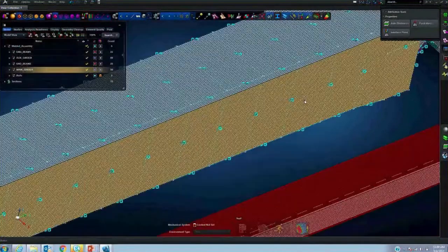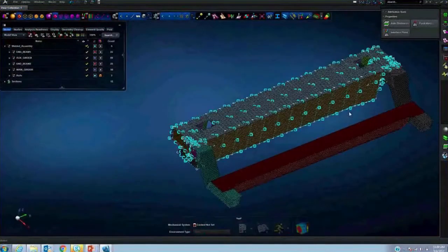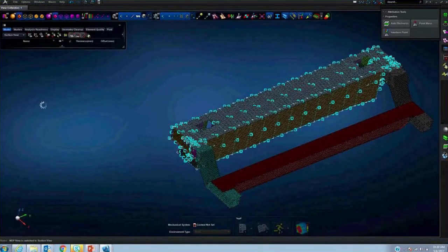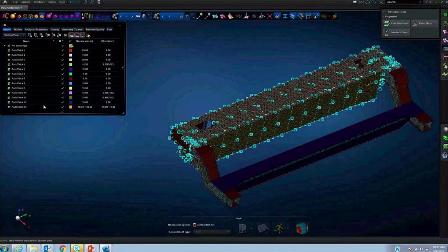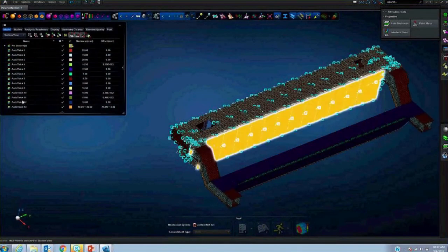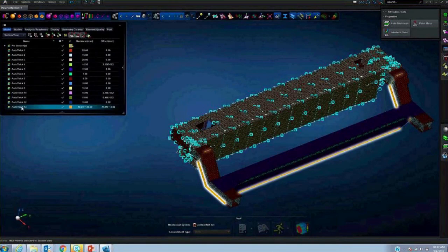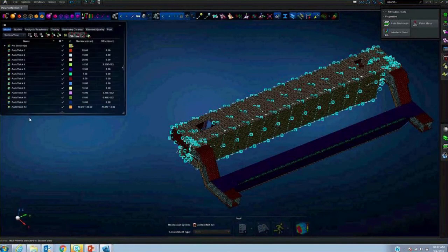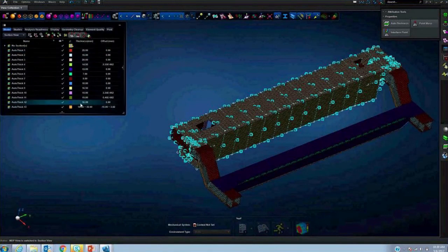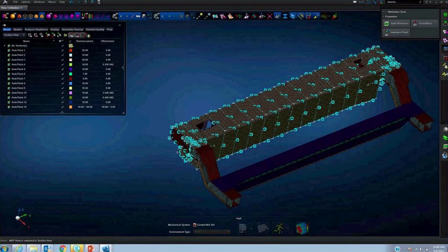All right? So, where is the section view? In the model browser, if you toggle this one to section view, now it will give you the different sections it created in this model. Even for hundreds of parts, it merged the equivalent thicknesses, and now we have about 13 section properties created, with their thicknesses and offsets.